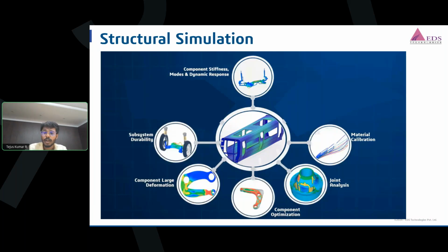Whether the component is a car body, a bogie frame, a suspension bracket, or couplers, engineers should predict the stresses, deformations, and potential failures across every location. This significantly reduces redesign at later stages, when you have already manufactured the product or built a prototype. So before that, you evaluate in the virtual phase.